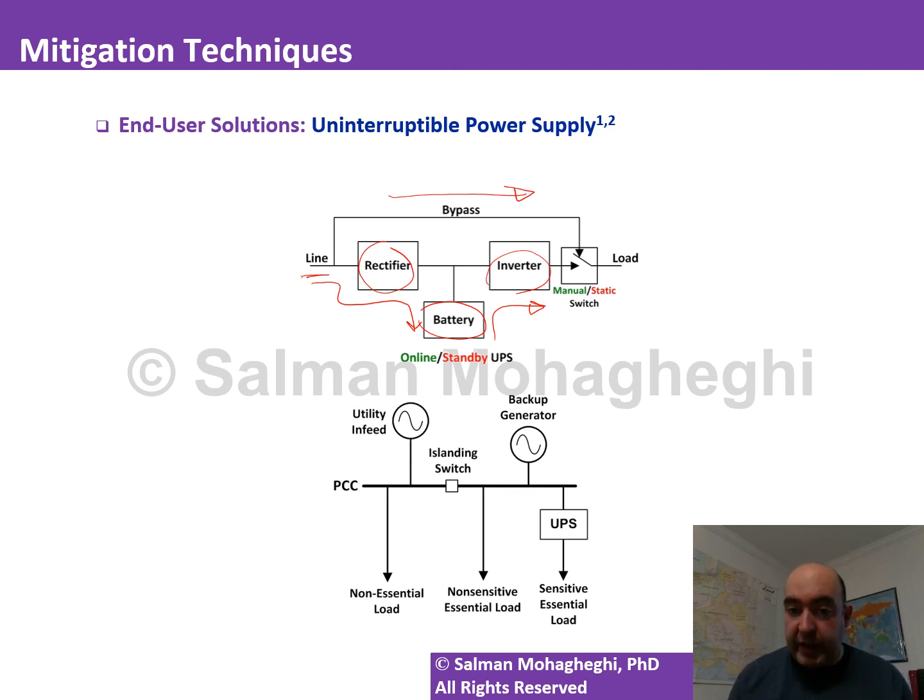This will give you high reliability, of course, but at the expense of higher cost, more wear and tear, and more losses, because the rectifier and inverter have losses internally, and also, as you know, batteries have a cost associated with them, in a sense that when you purchase a battery, it can go through a certain number of deep discharge cycles. So if you keep using it, that means the lifetime of the battery is going to be reduced. But for certain loads, this is a risk we're willing to take because they're very sensitive.